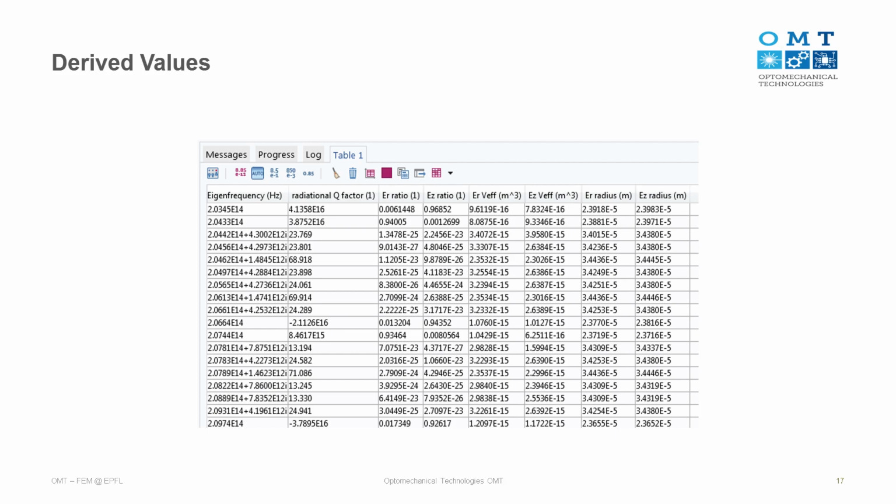Because you have the EZ component giving you almost close to 1, which means it's like 96% of the wave is inside the overall core area. And again, another one, pretty high level, which means this can be the fundamental, and this is sort of the high order mode. And also, you can define the effective mode volume, so it's 10 to the minus 15, minus 16, whatever. It depends on your geometry.